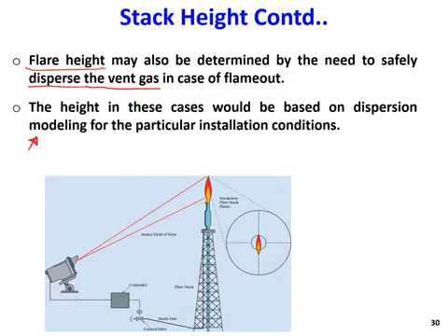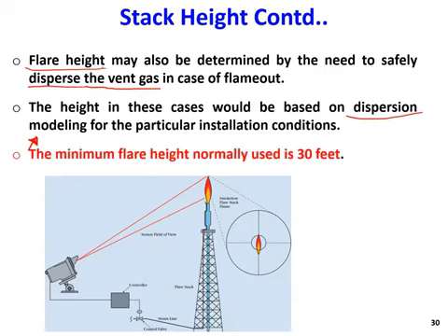There are some models, some equations, some standards that are used to consider the amount of gas and the gas dispersion, and based on that they will design the flare height. So this is also important. The minimum flare height is normally 30 feet. This is also very important. The minimum flare height is usually 30 feet or about 10 meters.